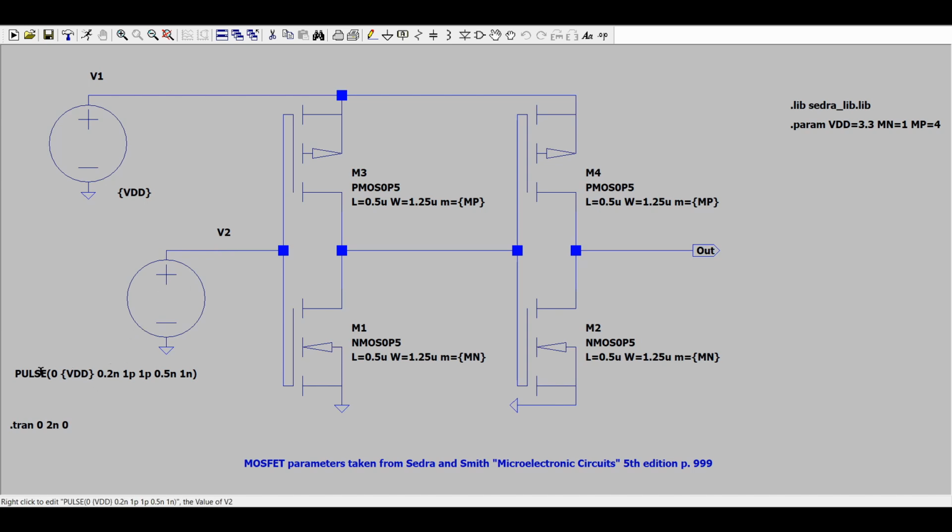This time I'm going to put a high-speed pulse into my simple inverter here. And I'm also going to load it with the input to another logic gate. In this case it's another inverter, but the point is, if the output of this inverter does not have to drive anything, then it's a lot easier for these FETs to supply the necessary current needed here. As soon as a logic gate has to drive one or more other logic gates, its performance changes. And by the way, we will learn later that this means you cannot take the output of one logic gate and let it drive 100 other gates. If you did that, you're just not going to get the performance you'd expect at all, because each gate loads it up, makes it harder for this FET to switch quickly.